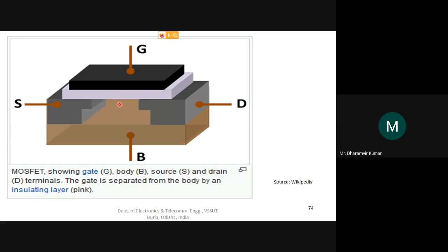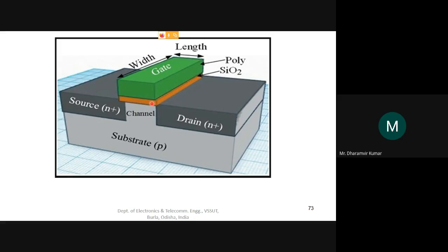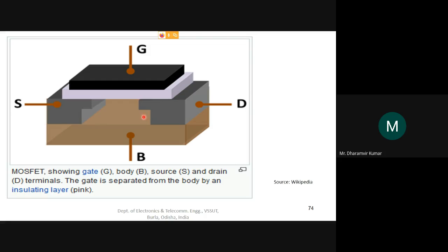Okay, and look at this, the drain terminal is not of the same shape as it was shown here. Here we had shown the drain region to be a perfect rectangle in shape. The source region is also a perfect rectangle in shape when we look from the front. But here this is not rectangular in shape. This one, a thin edge is coming out in this fashion here, and a similar and symmetric edge is also coming out at the source side.